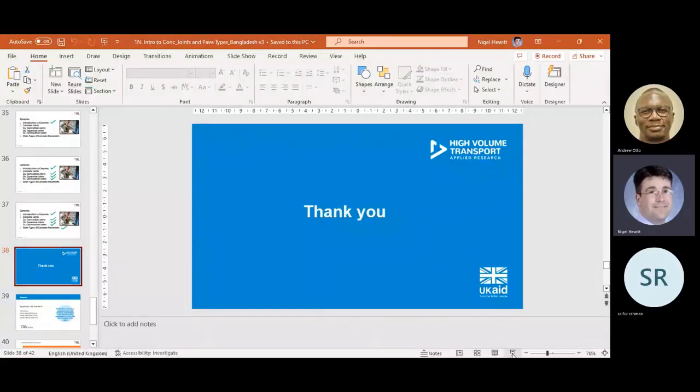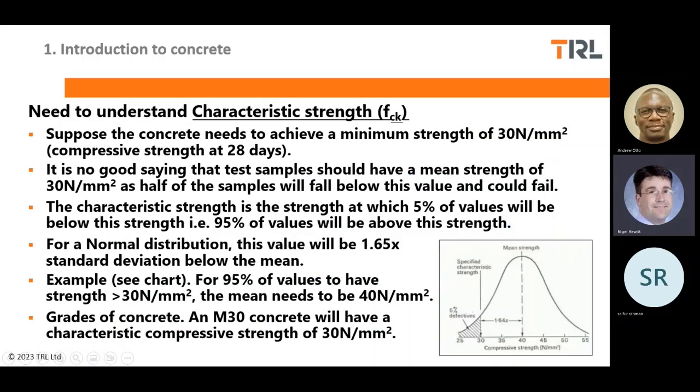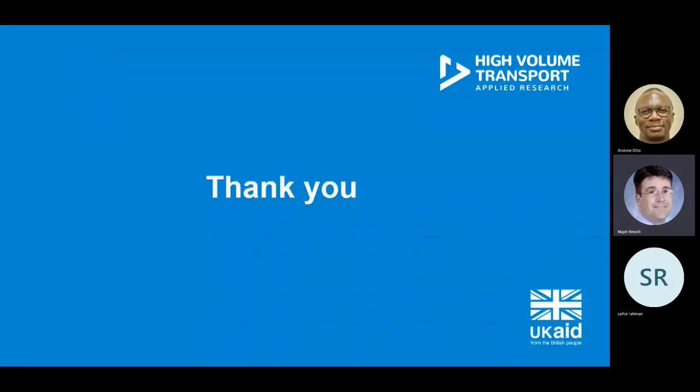In most pavement designs, you have designs for thickness of concrete without shoulder and with shoulder. We would always recommend having a concrete shoulder, whether it is an integral part of the slab width, or whether it is laid as a separate narrow lane, but tied to the main lane. So the trucks don't run near the edge of the slab, because that's where it's weakest. So you need that sort of gap where the trucks don't run.